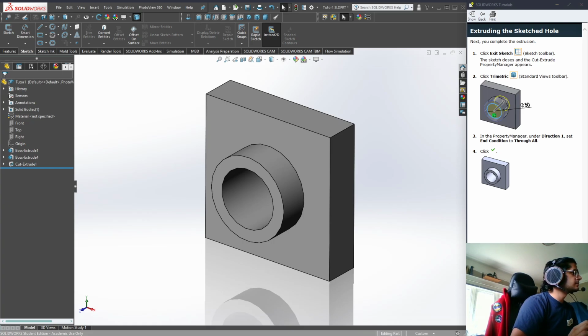Start back. Oh, okay. Hit escape, because you had that sketch selected. So now we go to features, top left, extruded cut on the top. Select the top of this circle. This? Yep, that's the one.